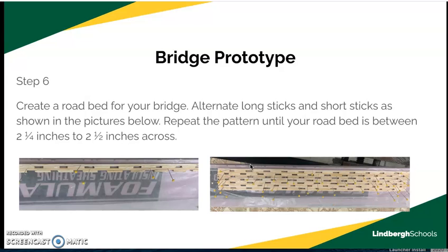Once that's done, then you're going to create the roadbed. And the roadbed on this bridge, I don't want it to be just sandwiched together solid material. This will make it easier as well to run the bolt through the middle, because we will have some little spaces where we can easily drill up through the middle to run that bolt through. You'll have a solid length stick, and then you'll have some shorter pieces in between. So the roadbed, as you can see in this visual, is not actually a solid roadbed. You're going to have spaces in between.